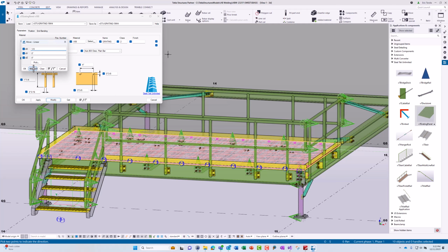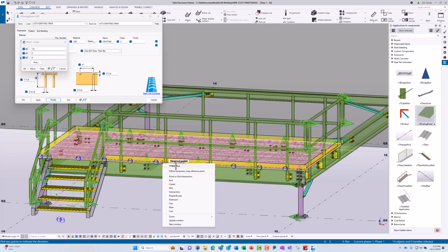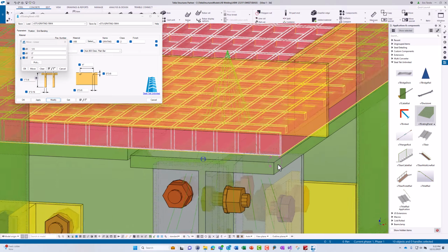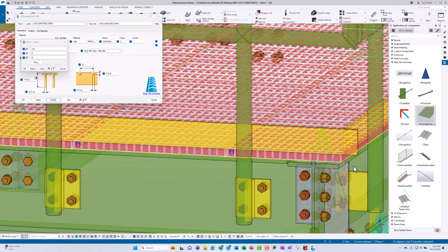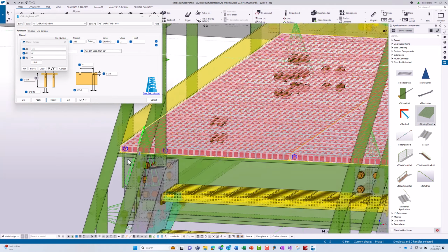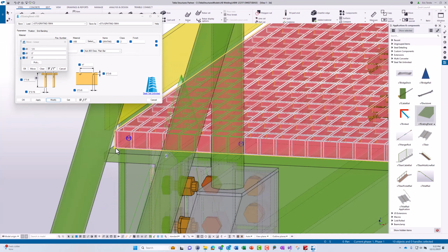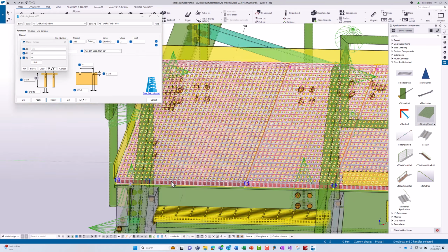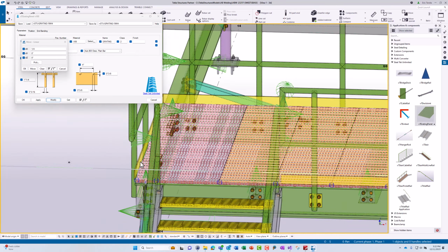You can see this xTGratingPanel plugin makes it very easy to lay out your panels exactly how they should be created. The drawings will reflect the panels accurately, and making the cutouts to the bearing bars the correct size is easy and quick. This makes your grating layout tasks much simpler and easier and helps eliminate shop errors and the ordering of inaccurate grating panels.